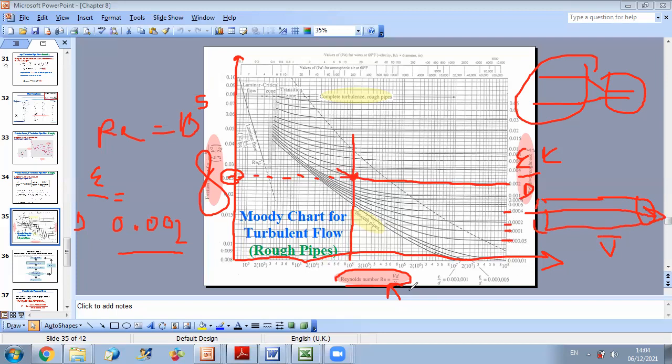Here in this Reynolds number, you use the average velocity in your flow. So if V is not changing, d is constant, and I have a certain pipe roughness epsilon, then in this duct I can compute the friction factor.